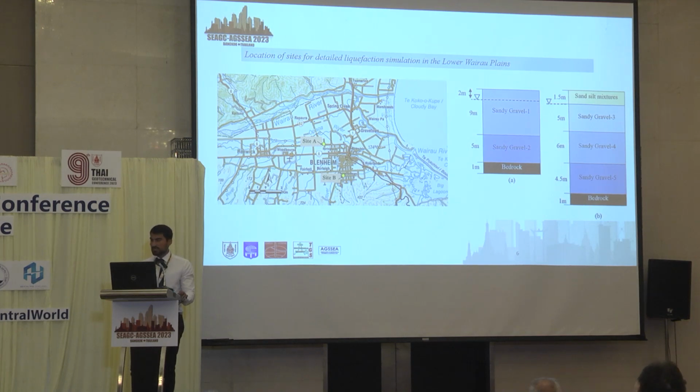For site B, the stratigraphy was a bit more changing, and the silt and sand was also mixing into the gravel. And again, one of the main criteria was to see that the relative density is changing frequently from 3, 4, and 5, and then these depths were set to use in the Plaxis.